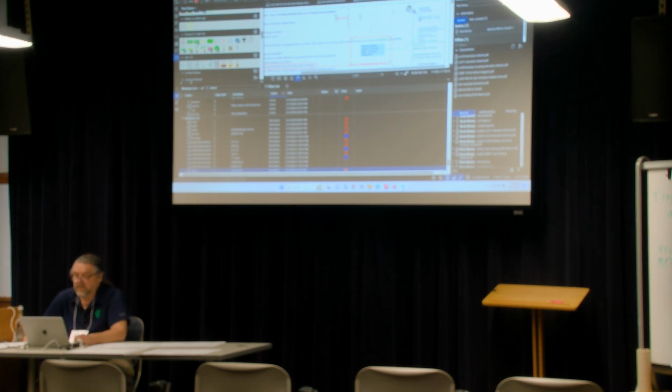So I've got who did this, and it's highlighted down here. It shows that it came from me, and it's red in color. From this list, I believe I can change the color. I just changed the line color to green, and the cloud color I can change too, if I wanted to.